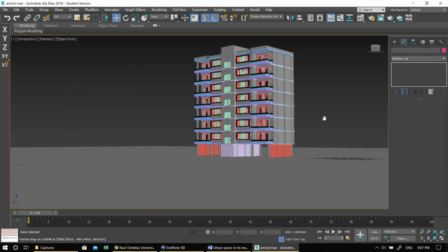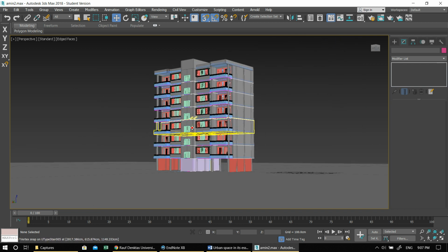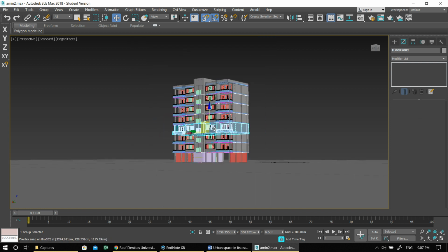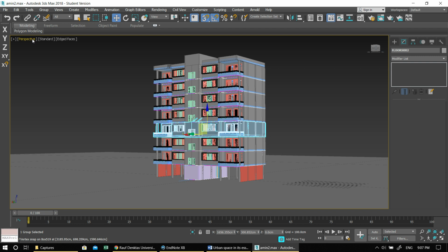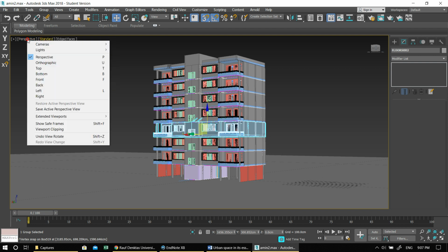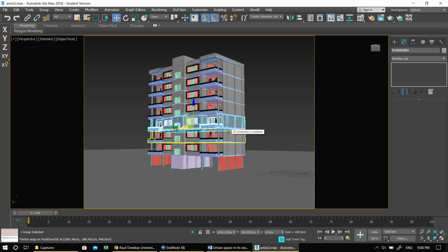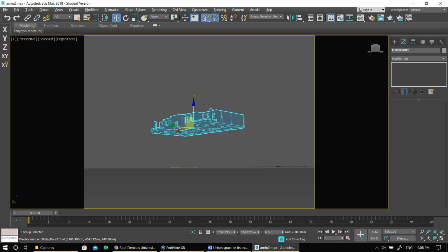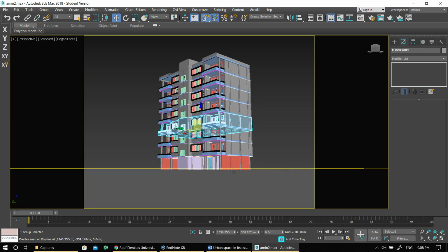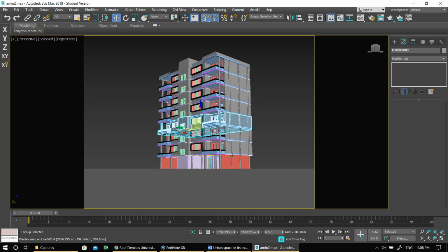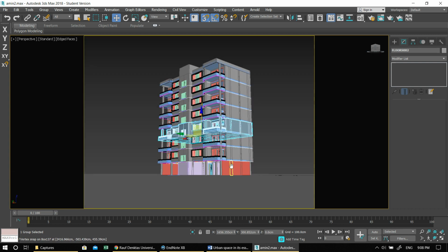If you want to see now, I want to render this. Pay attention closely here. If you want to see exactly what you see in the render view, we will talk about cameras after the midterm. But if you want to see, you can come here under perspective and say show safe frame, and then it will show you what you will get in the render view. So let me just go ahead and find a good human eye perspective. All right, so it looks fine now.